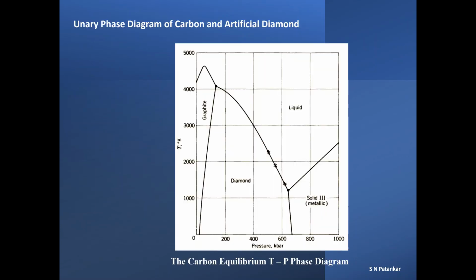Allotropy can be induced not only by increasing pressure or temperature but also by combinations of both high temperature and high pressures. High temperature and pressure combinations have been able to produce diamond artificially from graphite. The TP range where diamond exists stably is shown below in the carbon phase diagram. As per the diagram, at ambient temperatures and pressures diamond is unstable, though the time necessary for its reversion to graphite under these conditions is sufficiently long, geologic timescale.